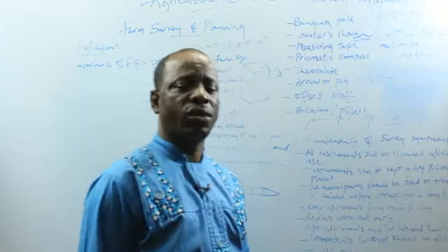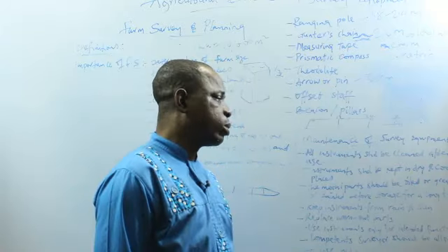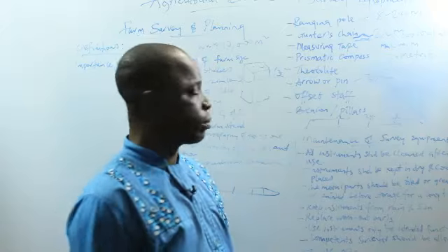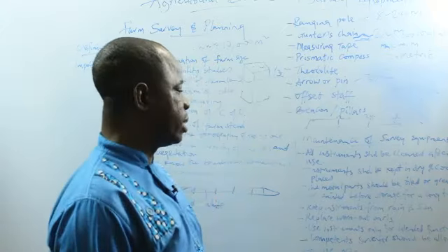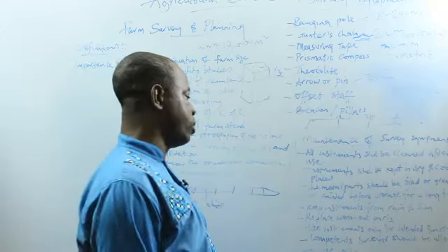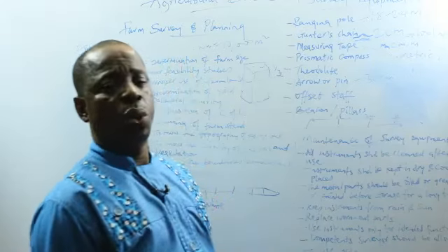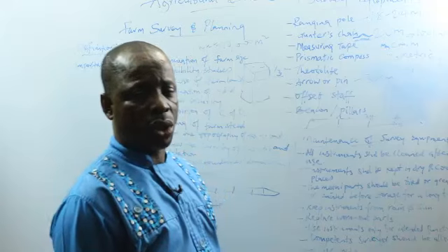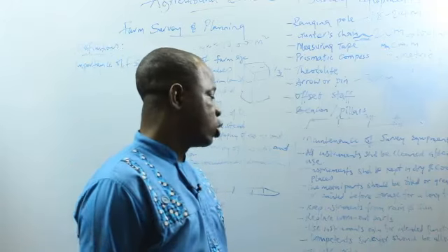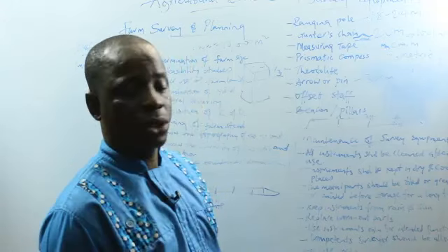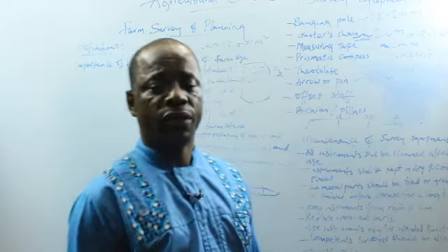How do we maintain our survey equipment? Number one, all the instruments should be cleaned after use. The instruments should be kept in a dry and cool place after use. The metal parts should be oiled, greased or painted when storing for a long time. Instruments should be kept from rain and sun. The instruments should be kept away from children too.